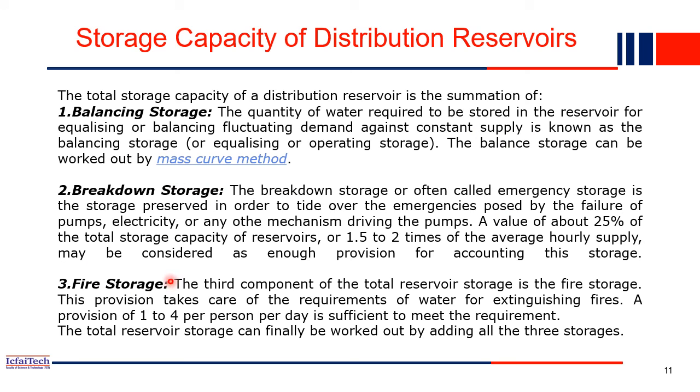And the last one is the fire storage. During a fire we need a large quantity of water in a small duration of time. So that also should be stored in a reservoir. If you add all these three, we will get how much total reservoir storage is required for the entire city.